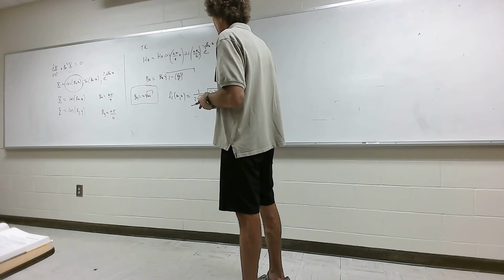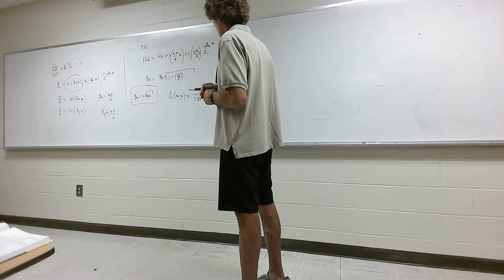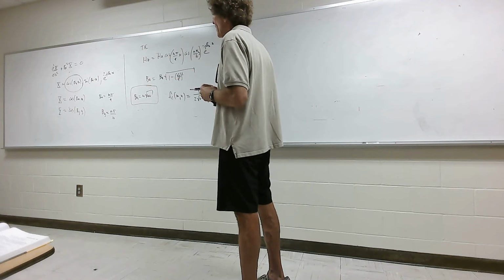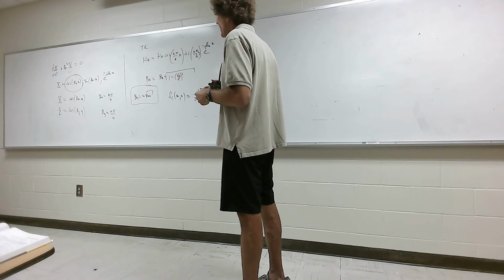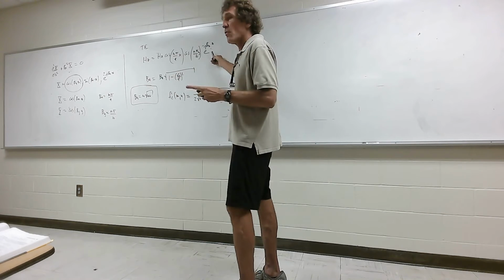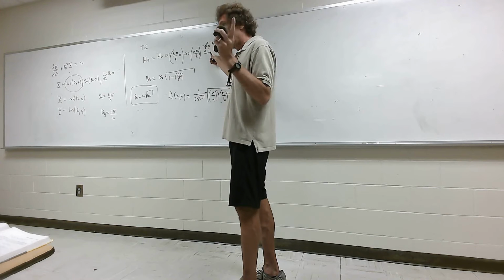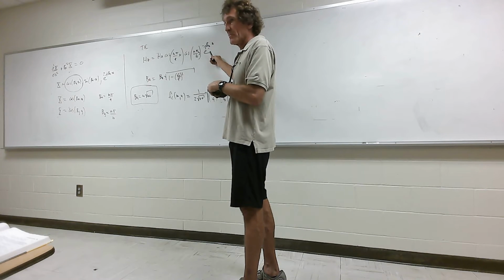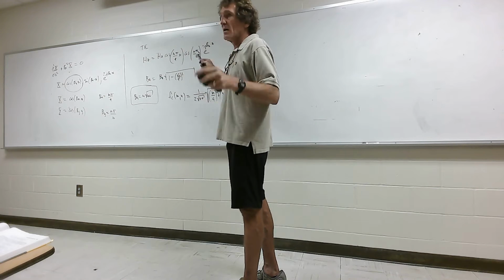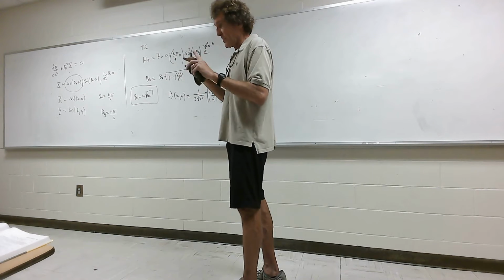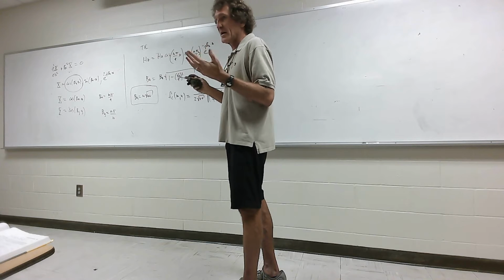That's the cutoff frequency, that's HZ. He shows in the book the values for E and for H, for EX, EY, EZ, and everything like that. When you actually have this form, you can take the curl of H, and you can find out from there every single one of the other field components. You can do it, all right? Takes a while, it's irritating, he does it.